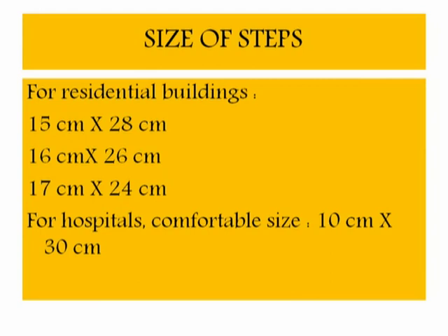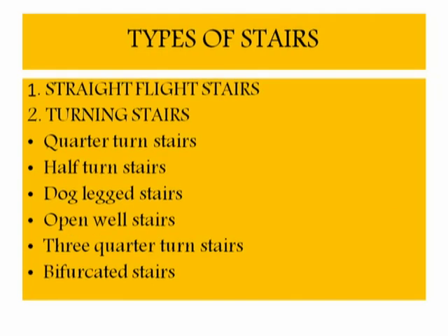Now let us see some dimensions of the size of the steps. The normal dimensions of the stair are 15 cm riser and 28 cm tread, 16 cm riser and 26 cm tread, 17 cm riser and 24 cm tread. For hospitals, the comfortable size provided is 10 cm by 30 cm. So these are the common sizes of the steps. Normal size is 15 cm by 28 cm.